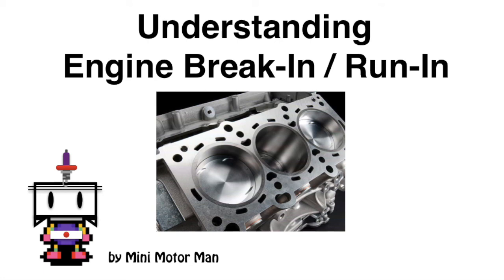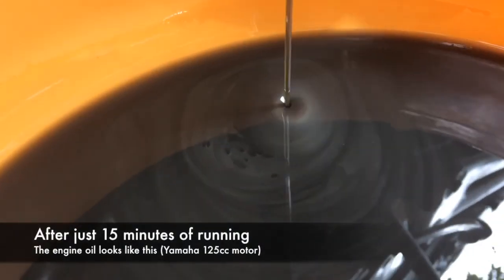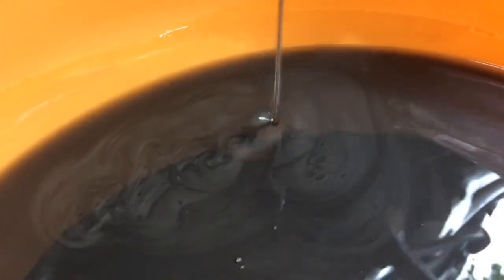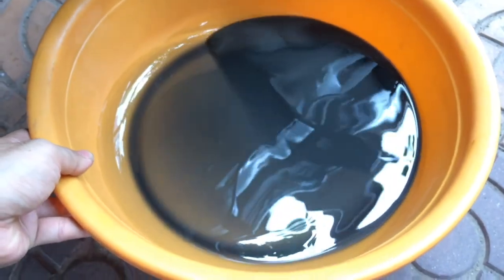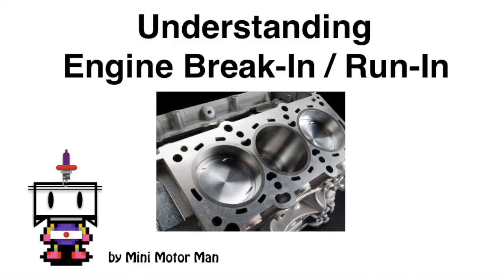But a quick note, however, before we go, the only thing I like to do as a little extra on top of people's instructions is, if you have a small oil capacity engine, like a Honda Super Cub for example, to change the oil after the first 20 minutes of warm-up and riding. The reason is because the roughest particles are going to be worn off in these first 15 or 20 minutes, obviously, it doesn't have to be exactly 20, and these particles will be suspended in your oil. Now, while I doubt that has a big effect, it always has given me peace of mind to watch all the glitter and metal drained out immediately.